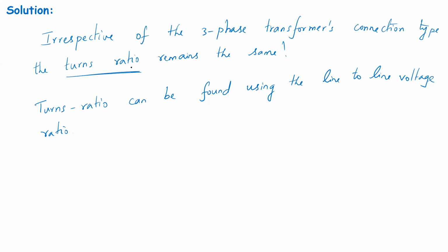And it is because of this reason, whenever we want to solve a problem in future for a transformer circuit, and if the equivalent impedance of the transformer is known ahead of time, we don't have to really do all the delta to Y conversions. We can directly replace the transformer with its equivalent impedance, because we know, irrespective of the connection type, the equivalent impedance of the transformer on a per phase basis is going to remain the same. And that is the important learning from this example problem.